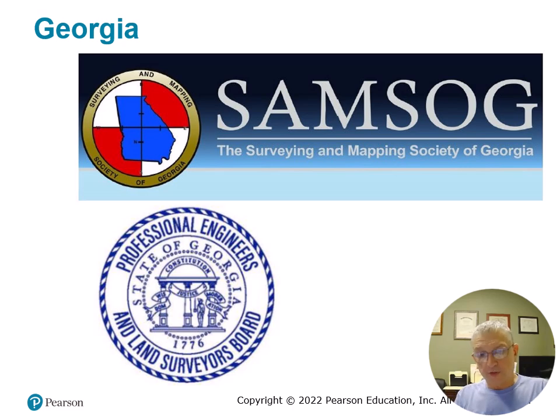So 1.13 is future challenges, the growing workforce, and the shrinking amount of people that want to do it. There will be more and more challenges, I think, as you see developed areas that people realize are moving or settling. Earthquakes change the relationship of benchmarks and property corners to each other. Places like New Orleans and a lot of areas around the coast, and even some places in the Midwest, as improvements are built and developed on top of property, they begin to actually settle into the ground. And it's almost imperceptible. It's almost like a little miniature tectonic plate.